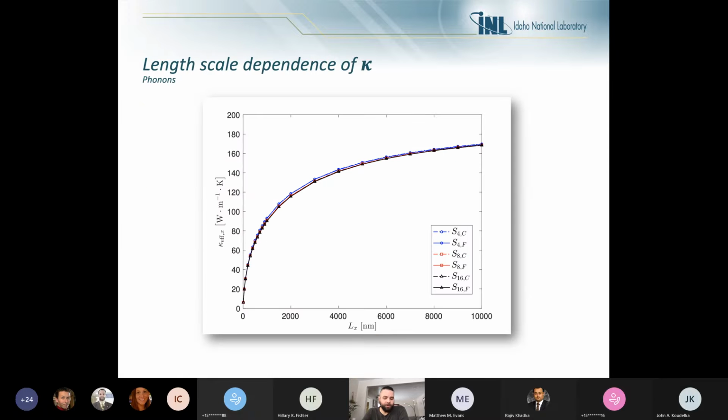I talked earlier about how different the physics are between nanoscale or smaller and then the macro scale. And this is to show you directly how that is. What we're looking at here is a graph of thermal conductivity in silicon. The length goes from about 5 nanometers up to 10,000 nanometers, so we go from the very small to about 10 microns, or 10 to the minus 6.